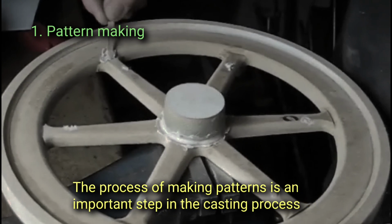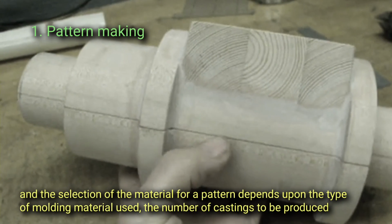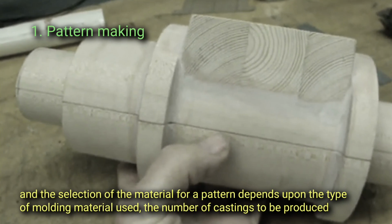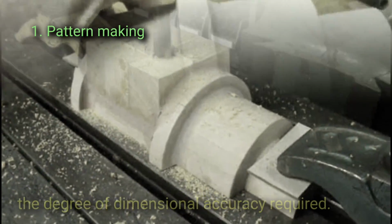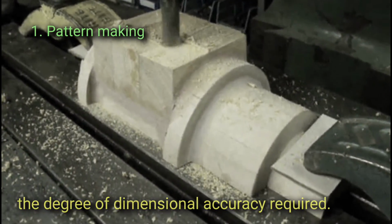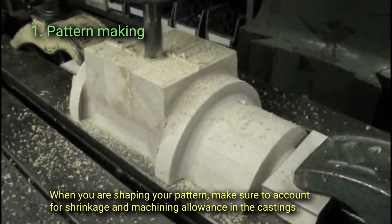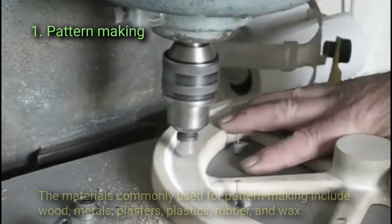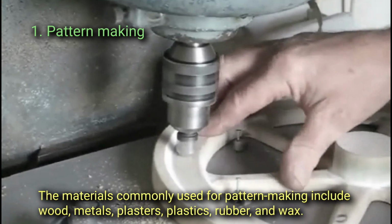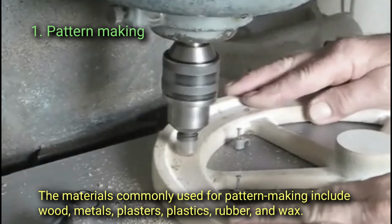The process of making patterns is an important step in the casting process, and the selection of the material for a pattern depends upon the type of molding material used, the number of castings to be produced, and the degree of dimensional accuracy required. When you are shaping your pattern, make sure to account for shrinkage and machining allowance in the castings. The materials commonly used for pattern making include wood, metals, plasters, plastics, rubber, and wax.